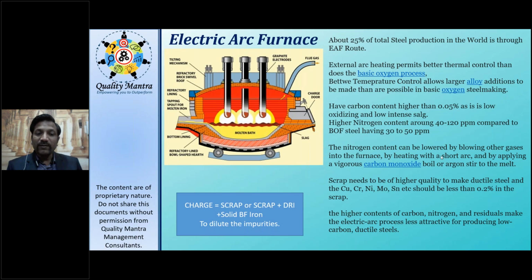So take out whatever TC comes to you tomorrow and see whether all these elements added together are more than 0.3 or not. It should actually be around 0.2 to 0.25%. If it is above 0.3, then there is a serious issue. It should not be at all. Normally it doesn't happen, but you all have a task: check the test certificate that you received from the wire rod supplier, how much of all these tramp elements are there.